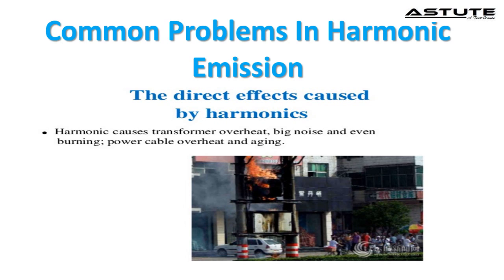Current regulators. Frequency converters. Voltage source inverters with pulse width modulated converters. Low power consumption lamps. Electrical arc furnaces. Arc welding machines. Induction motors with irregular magnetizing current associated with saturation of the iron. All equipment with built-in switching devices or with internal loads with nonlinear voltage or current characteristics.